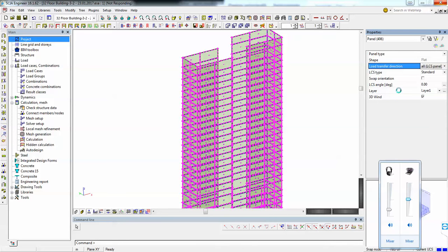Okay, now it's loading something. It's not bad the way you modeled with horizontal and with points. So if you want to get all the wind loads inside points that are concentrated at the end of the column, it's okay the way you did.